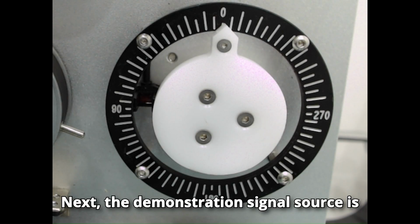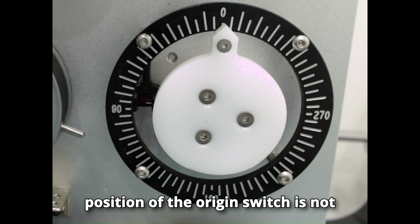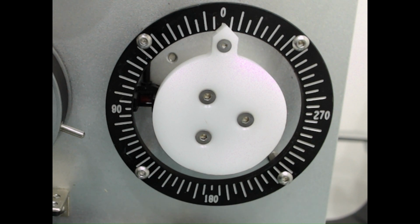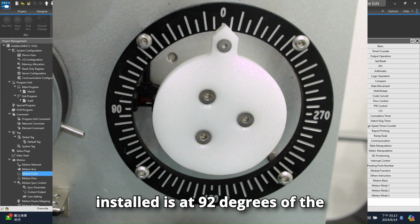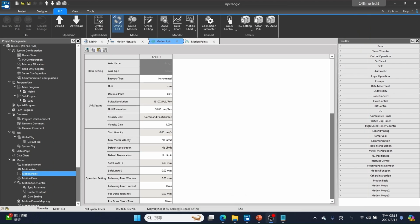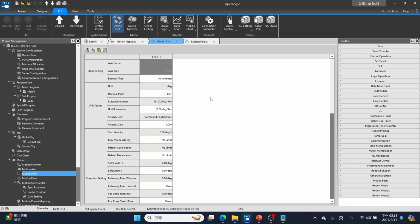Next, the demonstration signal source is from the PLC, and the installation position of the origin switch is not 0. The position where the origin switch is installed is at 92 degrees of the scale. The axis setting unit is changed to degree. 360 degrees per turn.